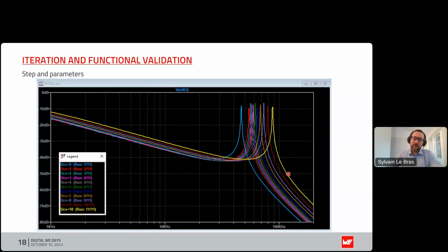And we can also see that the lower the voltage used to polarize our filter, the more effective it will be if we consider it to be a low-pass filter. So we can see here is a logarithmic scale. So the difference between this yellow curve and this blue curve is actually huge, even if it does not look like this on the screen.